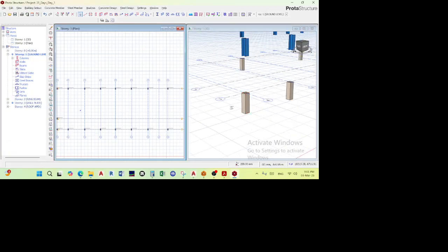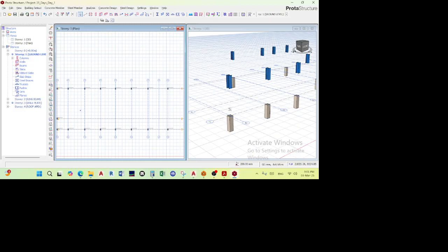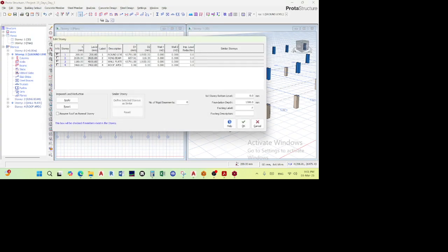But then now you have to do some simple subtraction. If the ground is at 300, it's at 300, isn't it? According to the building setup, it's actually 200. You can see here. If my ground level is at 200, and then my wall plate level is at 4,000, right?